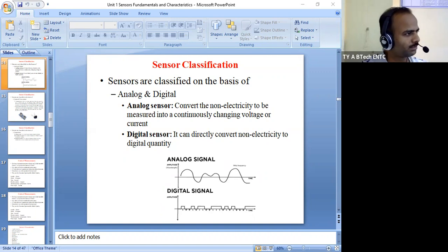No. For that purpose, if you have a clip-on type of ammeter, just like opening the mouth, if we press the button, initially it is closed, just open it. You just hold your clip-on ammeter below or above, any angle, 360 possible, close it and release the switch. So it measures like eddy current measurement or inductive type of measurement. So primary winding and secondary winding.